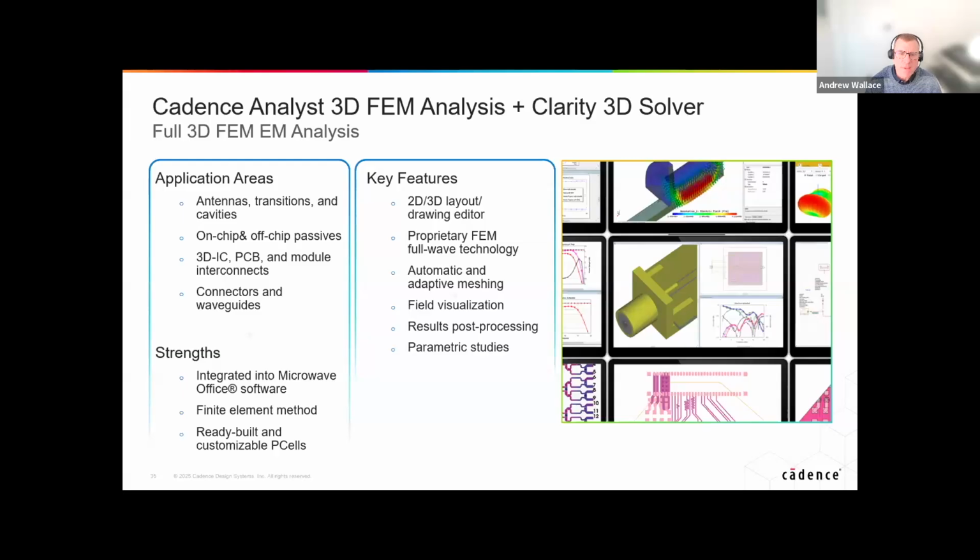And once again, EM extraction from that automated circuit level design and the physical layout that's generated can be pushed across to the 3D EM tool and simulated there automatically, with those S-parameter files brought back directly into the circuit schematic and included in your simulation results.